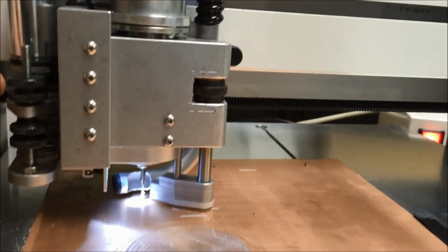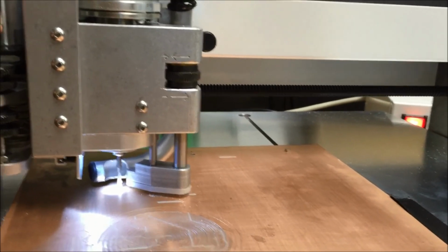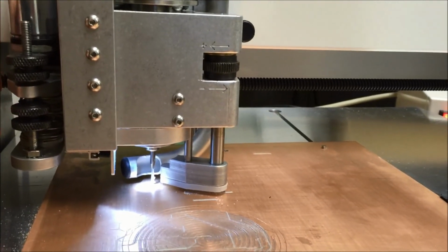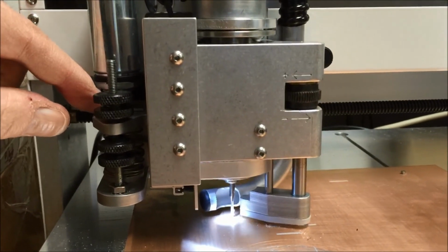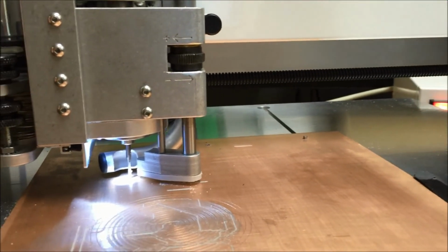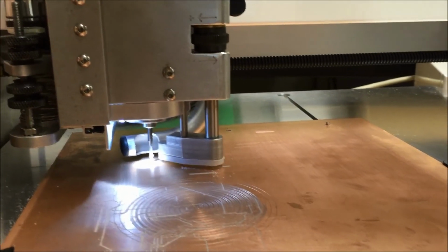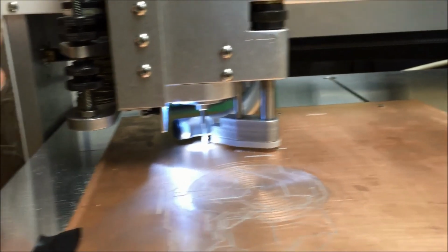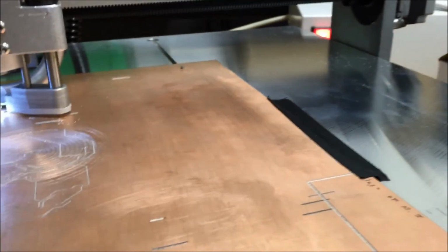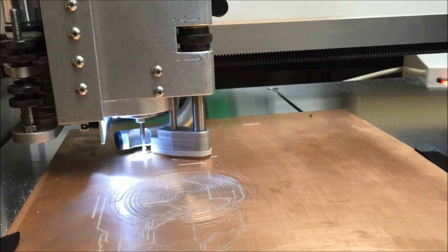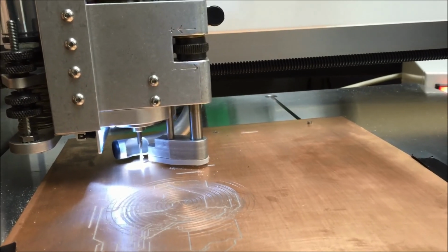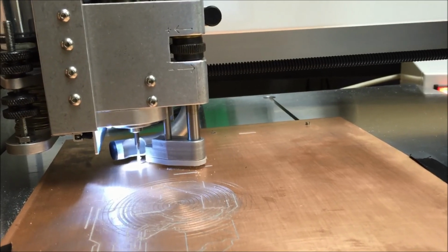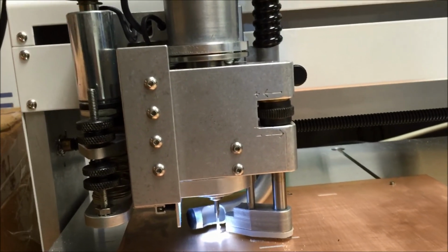So once you put in the bit, you can use these screws to also fine tune it, right? Exactly. That's exactly what I did. What's the procedure for adjusting the depth? There's a couple of ways you could do that. What I did was I jogged the machine off the work surface, and then used this to see how far the lower limit is. So all the way down, you make sure that you're not going to cut through the bottom layer of your material, and then you would set either the physical position of the bit head, or I think it makes more sense to just align it close and then change the two set screws.